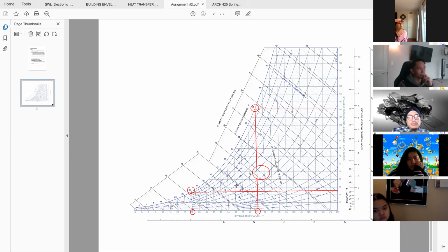A good point that our textbook makes is that with passive systems and natural ventilation systems, instead of just following the ASHRAE guidelines for heating and air conditioning, assuming that you're going to be climate conditioning your building 24/7, as people we are actually able to tolerate a little bit more in certain directions if we're not in 100% climate controlled conditions. The other factor is that people, based on where they're from and what they're used to, can be more sensitive to humidity or heat or cold.